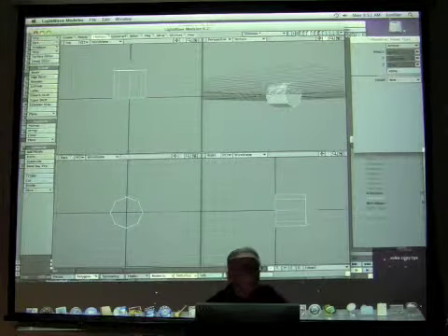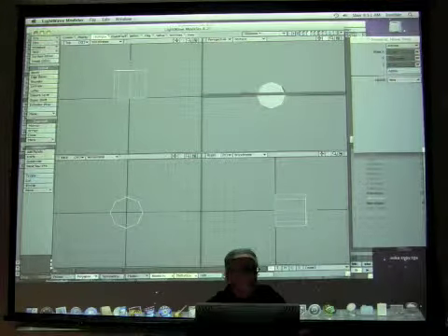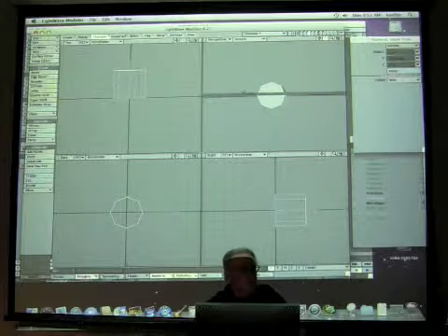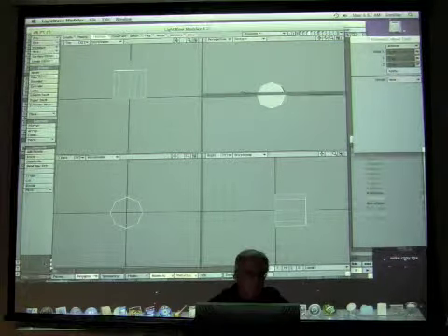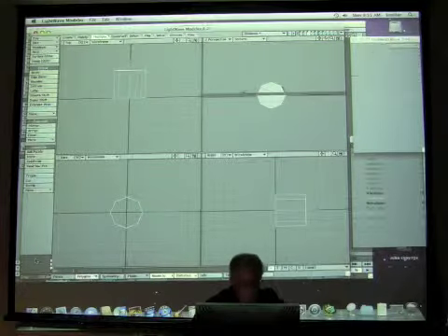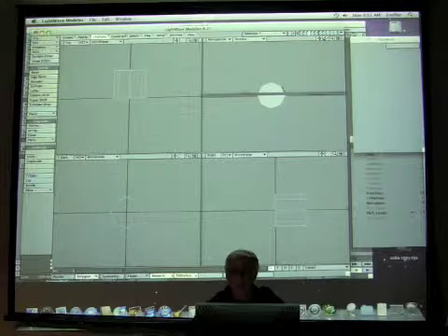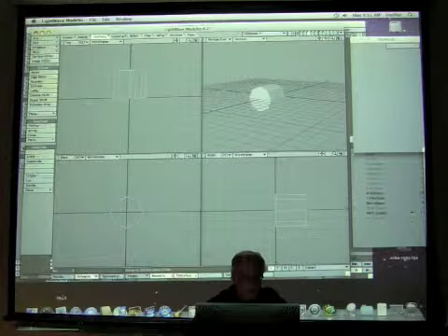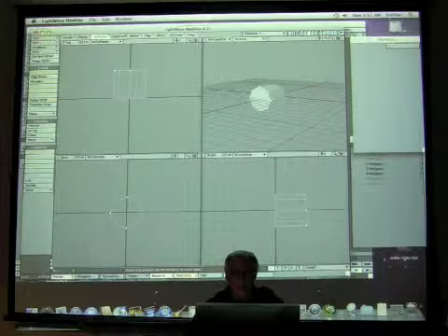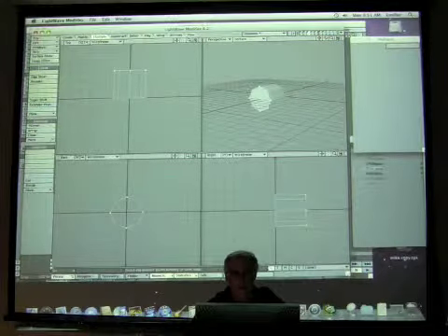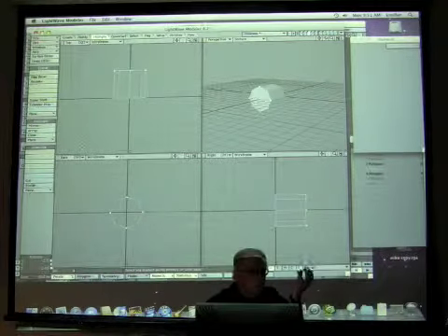Okay, so I have the same result that I would have had with the extrude tool. Now what I can do is I can switch to points. So let's deselect, let's hit T for move, let's turn it off. And now let's select points. So I'll switch to points. I'm going to select every other point as I did before. And I'm going to resize that end, and I'm going to bring them in.